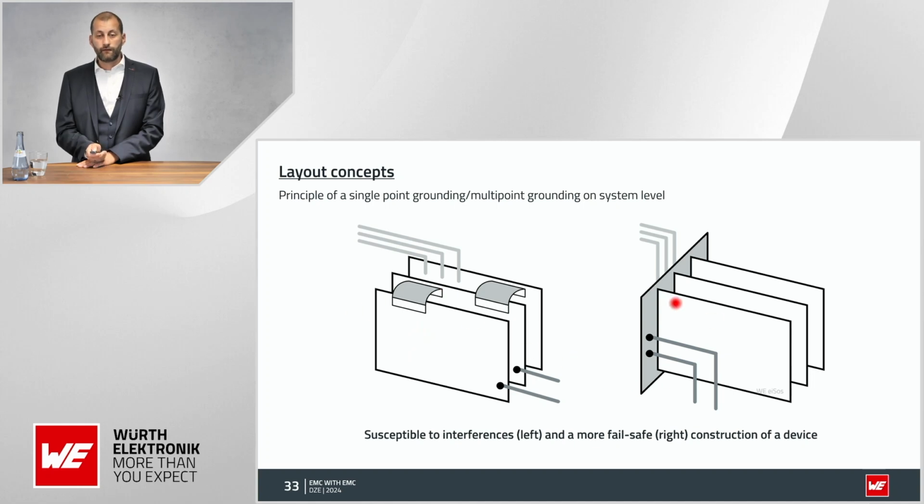Better in this case. If we have some problems on the cable, due to the ground plane, it will hopefully go the direct way out of your system. So star topologies are really good and really useful. The same goes for separating analog and digital parts on your circuit board.